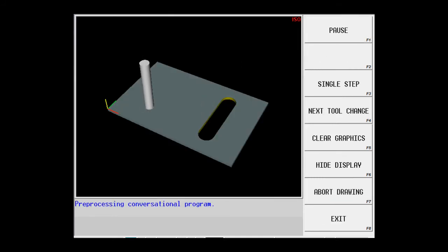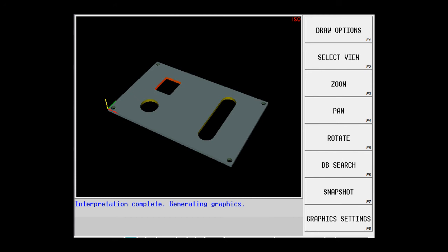Now if you look at the bolt circle, there are 6 equally spaced holes, and they are 200 thousandths in diameter, but they are not tapped. If you look at the 4 corners around that small frame we did, those are also drilled with the .2 drill, but they are tapped. So I'm going to do the bolt circle first.